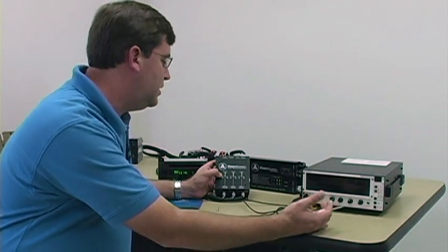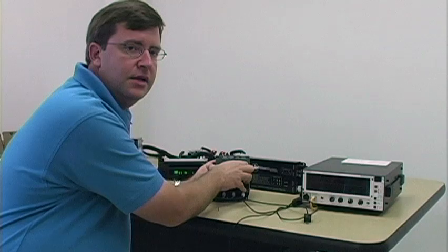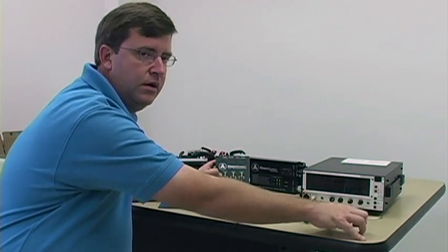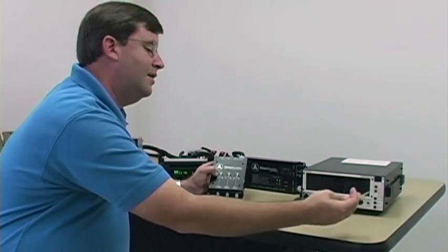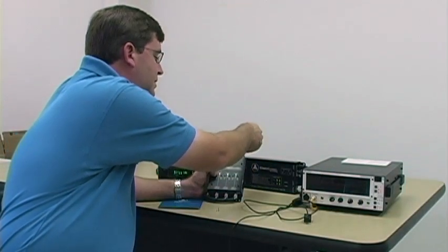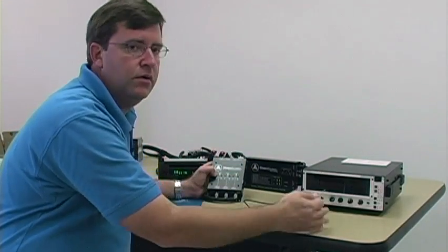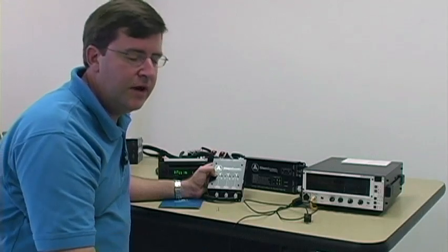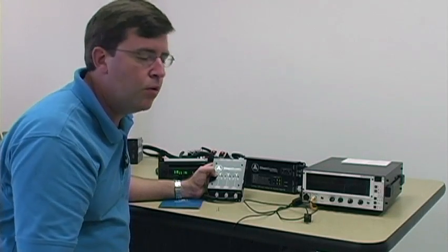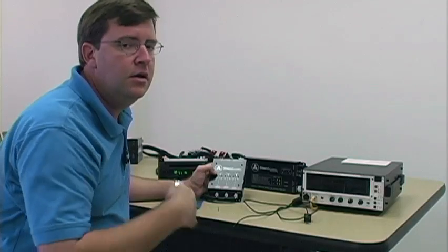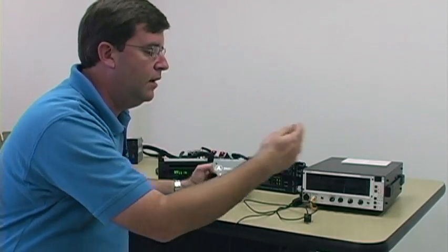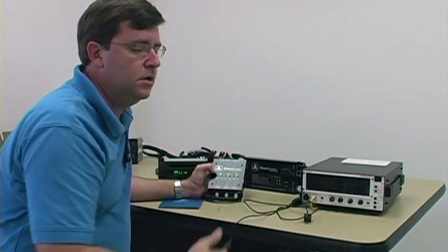In some really exotic situations, you may actually have a 3-way front and a 3-way rear in a car. In that case, you would need 2 SSIs to sum each front and rear section, and then you would need to take the output of the second one and splice it in to the harness that's feeding the DSP unit, so you have a distinct front and rear signal in the system with full fading capability. So if that happens to be important to the customer in that application, you can achieve that even when you have 2 3-way setups by simply using 2 of the units.